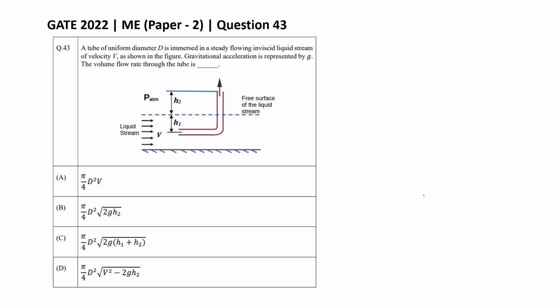Sir, if we get a problem from an orifice meter or venturi, then Bernoulli's theorem or like that. Yeah, orifice and venturi, I think we will do eventually. That is just hydrostatic pressure, right? You have to balance the hydrostatic pressures in the manometers in orifice and venturi, and then I think in venturi you have to apply the Bernoulli's. But yeah, you are right.